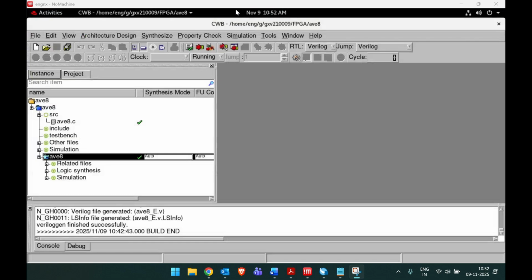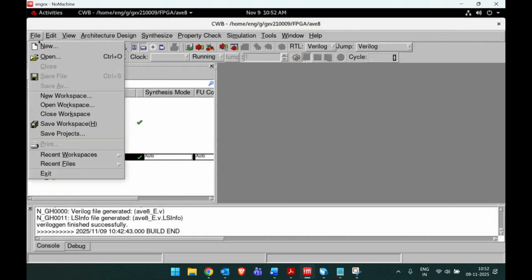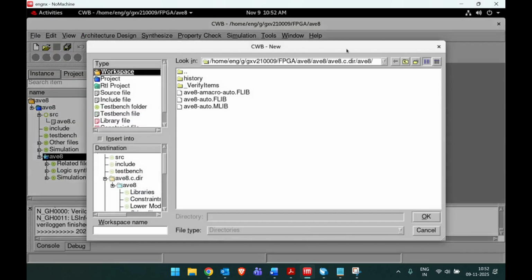Hi, in this video we'll see how to create a new project in Cyber Workbench and do high level synthesis and analyze the resource utilization. So first let us create a new project. Before that we'll create a workspace for the project.